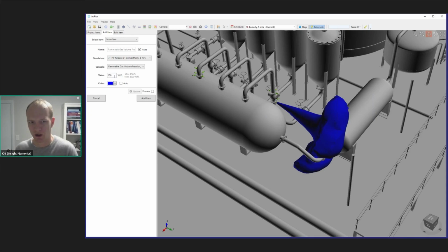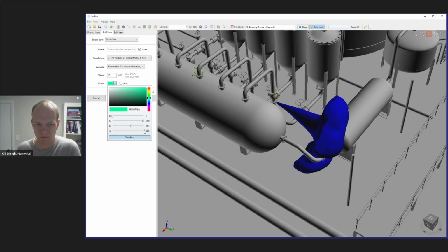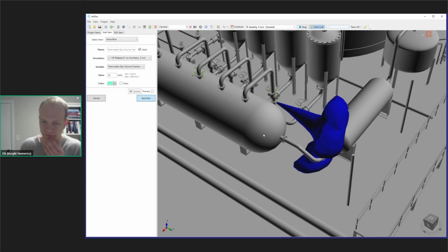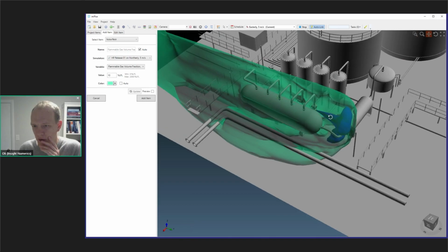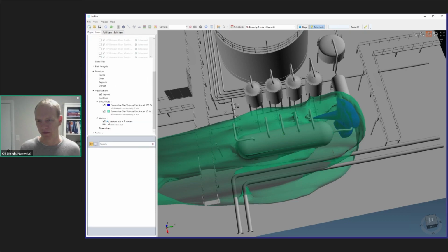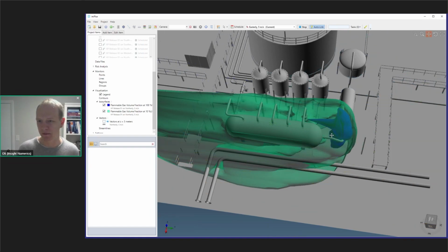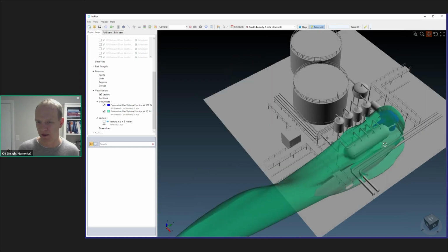Now, we can then look at lower gas concentrations. Let's say 10% LFL. Now, what you'll see with this gas cloud is that because we're looking at a lower concentration, the gas cloud impacts that vessel and loses a lot of its momentum and then gets turned around into the wind. You'll see, for example, that the vectors that we looked at before are flowing from right to left. So the leak opposes the wind direction, and the gas cloud then starts flowing with the wind through the domain.